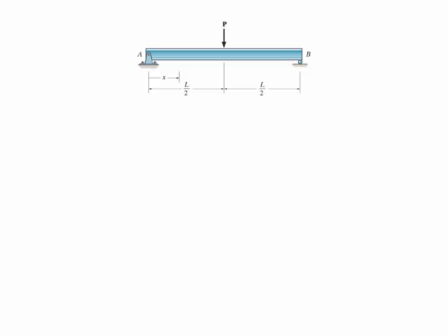In problems where we need to determine the curve for the deflection of a beam subjected to certain loading conditions, we are going to be using the discontinuity functions method. The reason is that most of the time you're going to see that the bending moment diagram is discontinuous. Like in this case, the triangular shape shown on the screen represents the bending moment diagram of that beam subjected to a load at midpoint. And that bending moment diagram is discontinuous at midspan. So the use of the discontinuity functions method is going to be useful here.